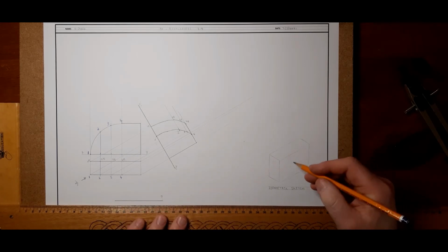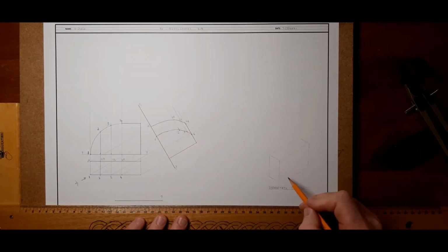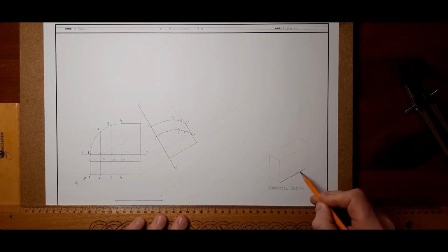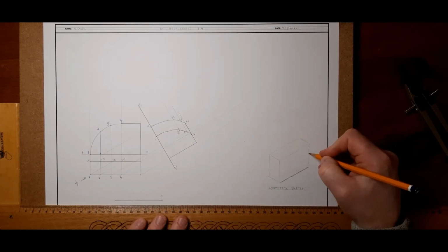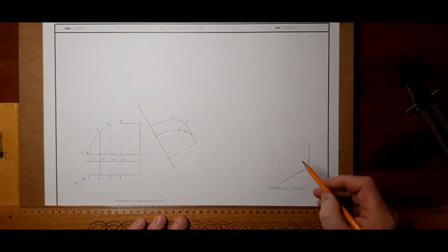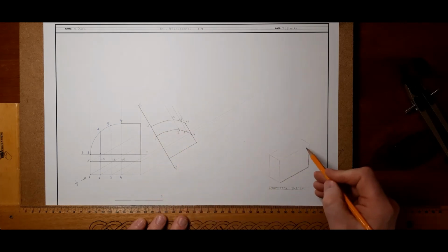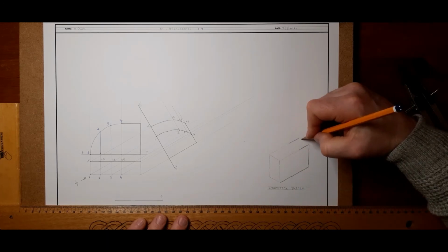So now I'm going to go ahead and I'm going to do my isometric sketch. So we can see up here, I set up the box already just to save us a bit of time. You should know well now how to draw these at this stage. So the bottom runs all the way along the bottom. The end goes right up to the top. That's the height of the crate. Then it comes out a bit here, a flat bit. You can do the same to the other side.